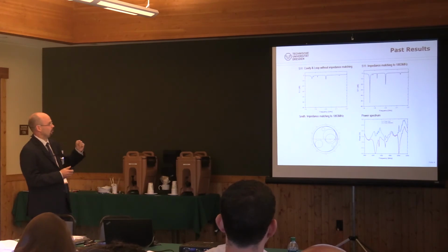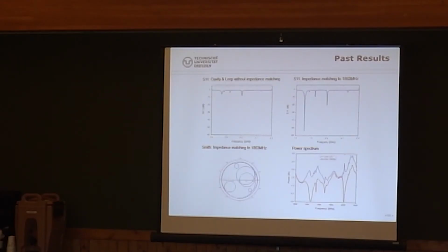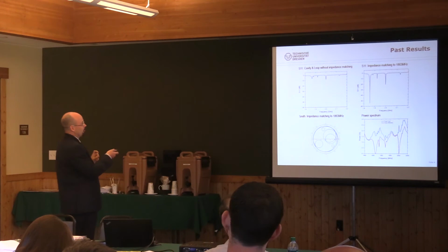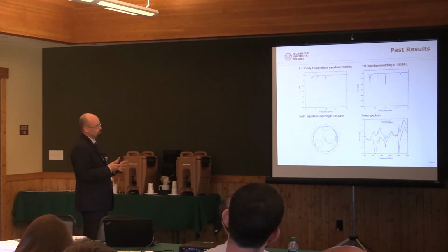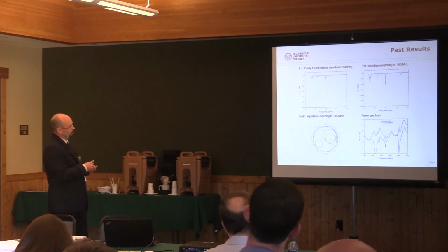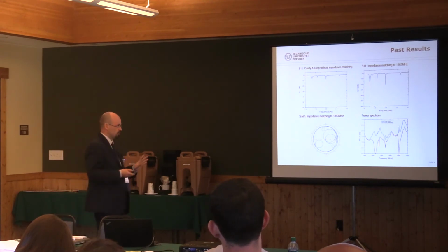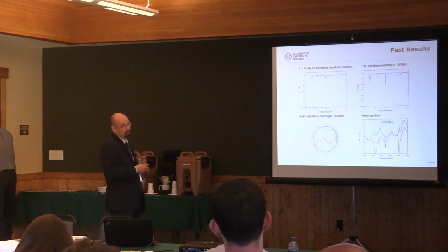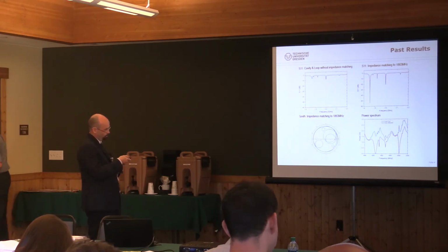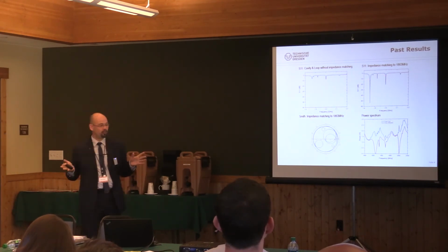Well, these are the calibration tables of our last cavity. Here you see the unmatched S11 frequency sweep done with our VNA. I have to mention, the antenna at this time was designed for a frequency of about 2 GHz. And with this 2 GHz designed loop antenna, we saw these reflection peaks at the unmatched cavity. We decided to start with just the first frequency we saw, which was 1863 megahertz, which is obviously not the best Q of all the frequencies, but we decided to start at any point.